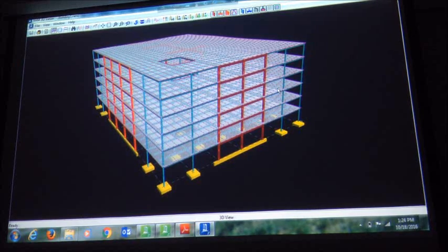So it's about 39 feet. So after third floor, in any way, you have to add a new member. So if you have to add a new member, you have to change the member. Why not we use a smaller column size? Because that column size above third floor does not have to take all the loads. Just takes a roof and whatever above it. So it can be reduced. Thank you. That's why.